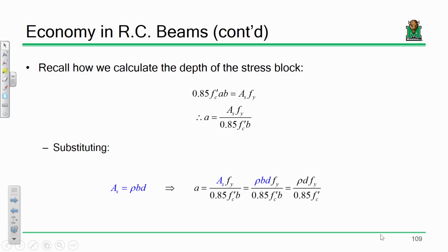And so we use that to solve for A. That was the term we don't know at the beginning of the analysis. We know the dimensions of the beam, we know the concrete's KSI, 4 KSI, 5 KSI, whatever. We know the steel grade, we know the area of the steel, but we don't know A. So we solved for A. So that was fine for analysis. When I'm talking about design, I want to look at this.